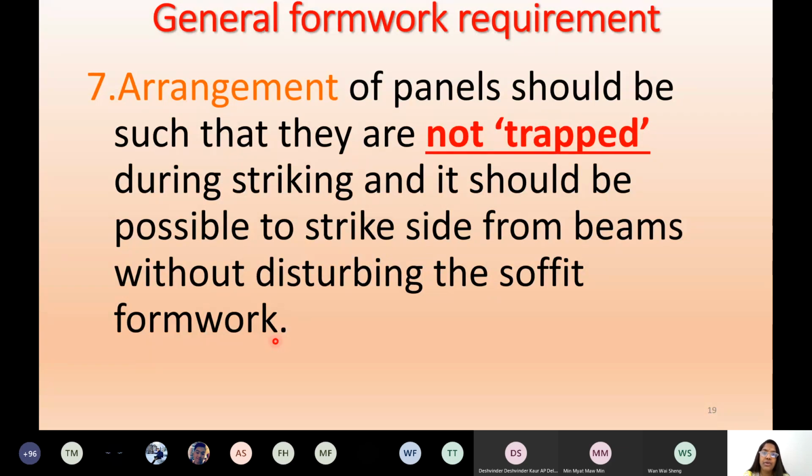When you remove, you strike and remove it, right? Because it is stuck together, the bonding is very hard. You need to give a blow so that it will get removed or stripped off from the surface of the concrete which you built already, which you hardened already, right?